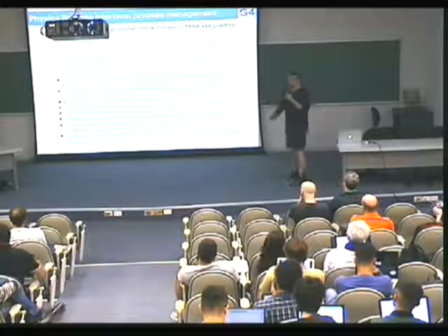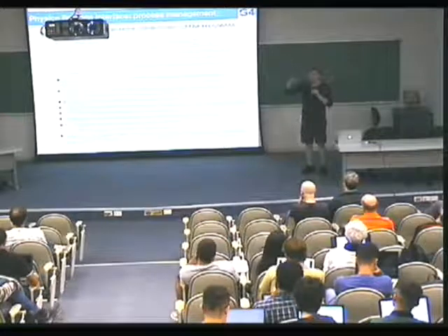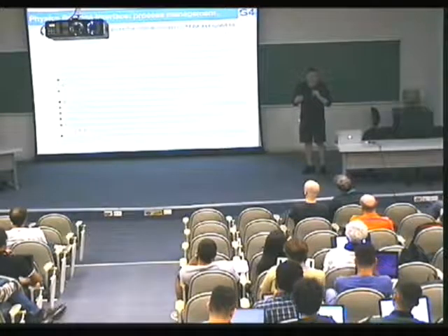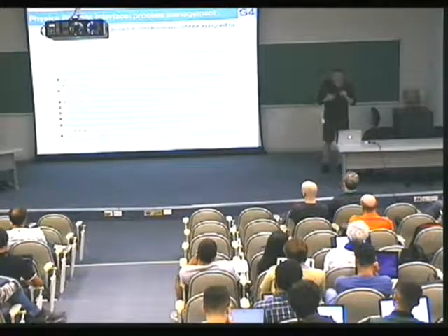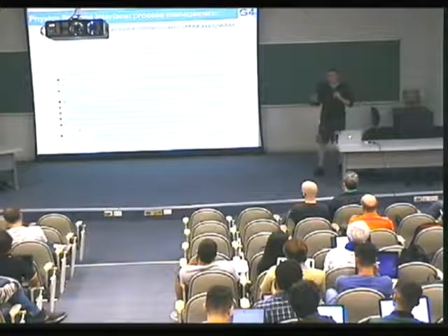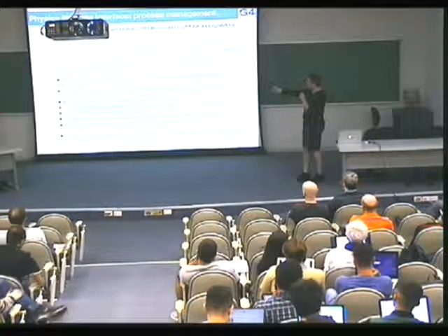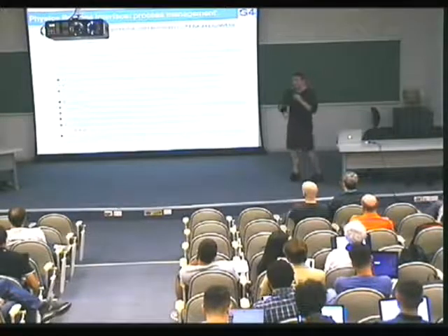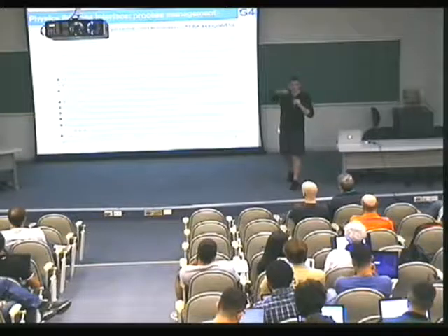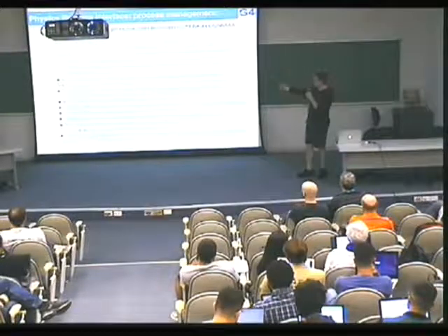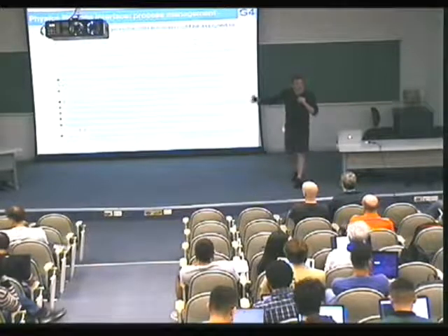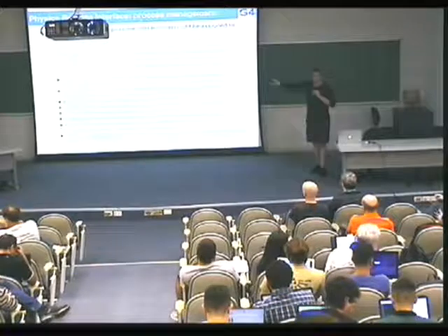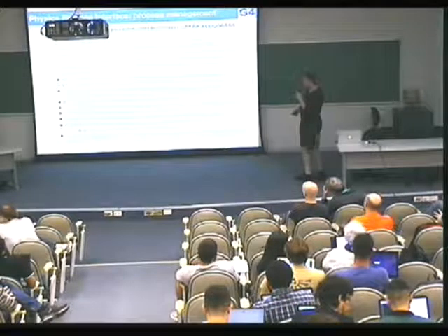Now, as you could see already yesterday, in the physics list we assign the processes to a given particle, so there are many possibilities. For example, in case of gamma, we saw that we can assign pair production, Compton scattering, and photoelectric effect. Each of them is a process. And actually, pair production, Compton scattering, and photoelectric are each of them a discrete process. It's happening at a given point. But you can think that in case of gamma, there are other possible interactions, like I mentioned, gamma nuclear. So in a complete physics list, you would assign also gamma nuclear interaction for gamma particle.